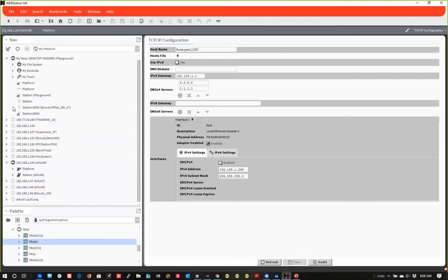When you deploy 100 VAV boxes, you'll set up a spreadsheet that's part of a template, and you probably would want to add your K factor and your min and max flow balancing set points as part of that. Then when you do a deploy, those fields will come up and allow you to make changes. Or you'll create the spreadsheet so each controller can have its own individual box size, K factor, whatever's required that's different from each of the boxes, so that it'll deploy the right set points for the right boxes.